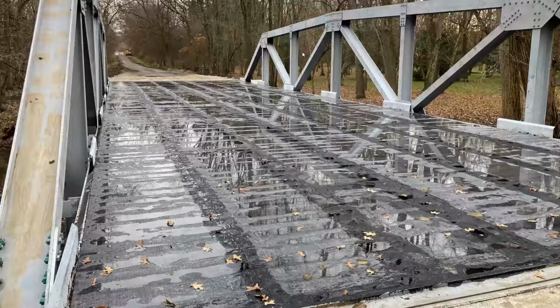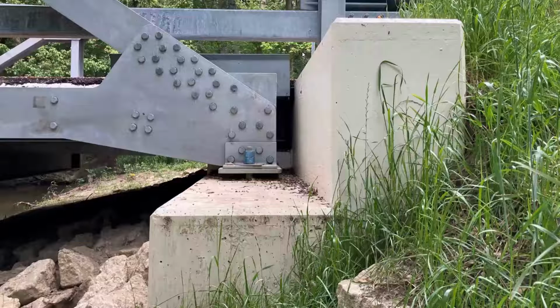Here's before paving. You can see the type 3 waterproofing was put down. It was packed down, then laid out over top of a stainless steel drip strip on the sides. And then this would be paved once it dries out. Here's a view of the abutment and its bearing and the abutment seat and step for the abutment seat beyond. You can see the asphalt paving and the drip strip on the right or up above the bottom chord there.